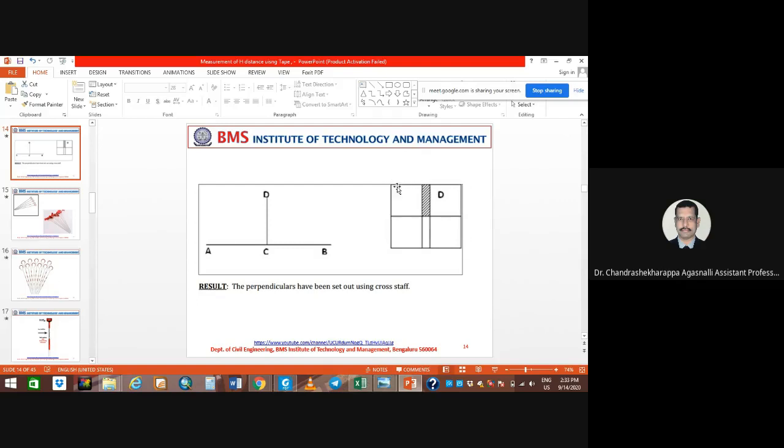These arrows we generally fix for the corner points of your surveying area, not for intermediate ones. Once you have aligned the intermediate points properly, it is not necessary to fix them with arrows. Arrows are only for the corner points. In between you can mark with paint, or keep something temporary like a stone or a small wooden stick.